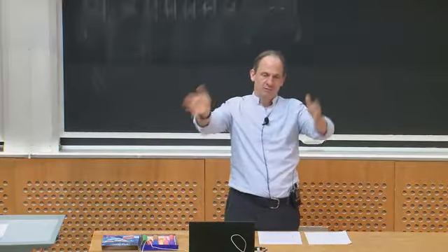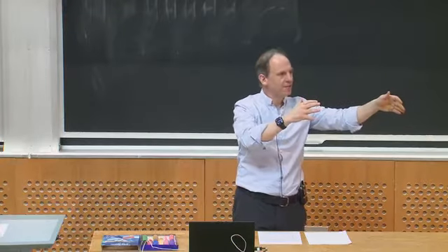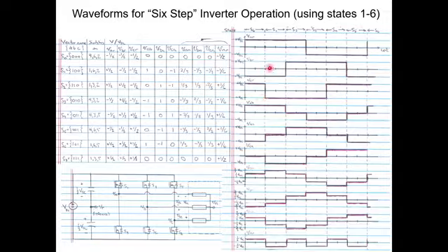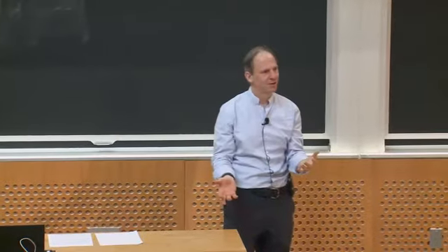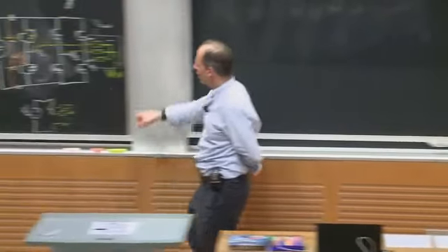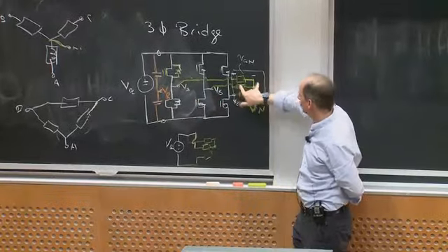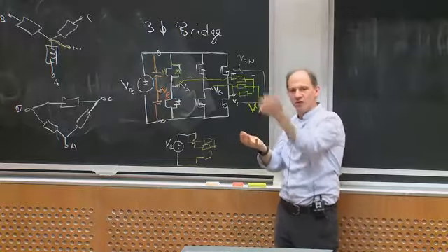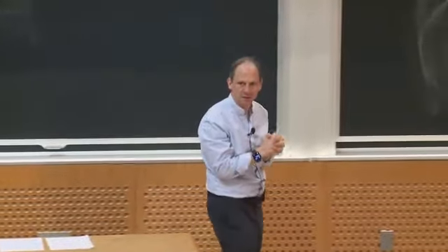The fundamentals are 120 degrees out of phase, but that means that the third harmonics are exactly in phase. So the third harmonics of each of these square waves add at the neutral, and you get a neutral voltage that bops up and down at the third harmonic. So the neutral contains the third harmonic and actually all the triple N harmonics. And so as a result, just as the line-to-line didn't have any triple N harmonics, neither do any of the line-to-neutral voltages. So if it's a Y-connected machine, the line-to-neutral voltage, which is really what's driving current in this thing, has no triple N harmonics. Okay? Does that make sense to everybody?